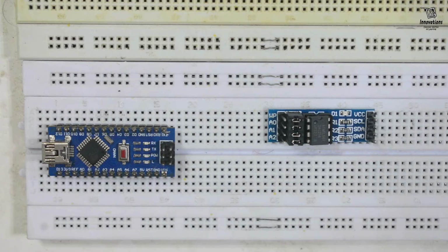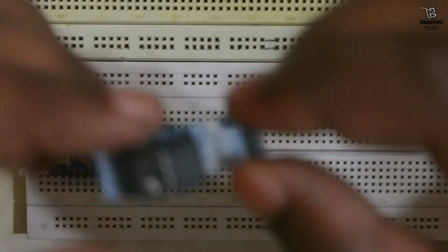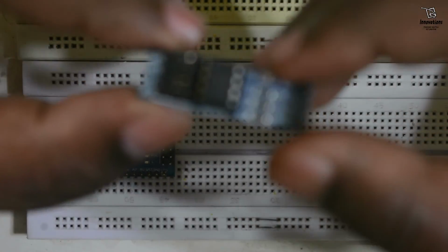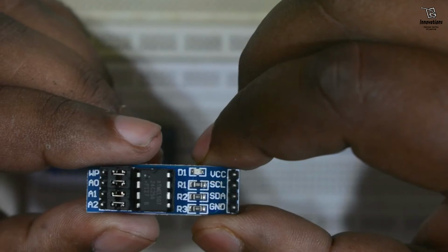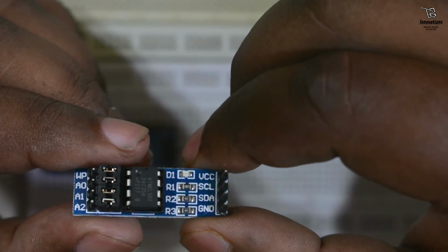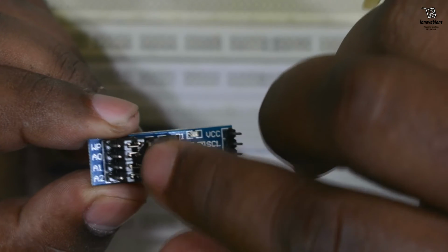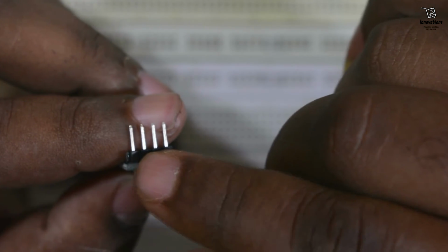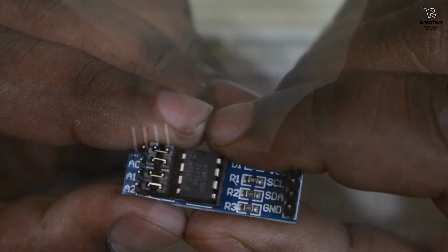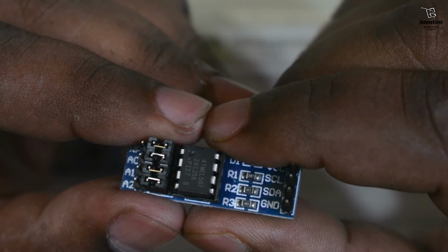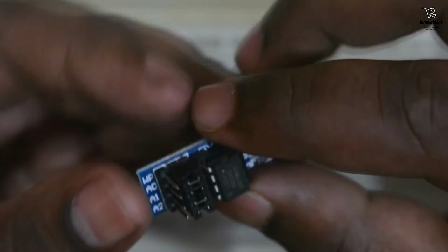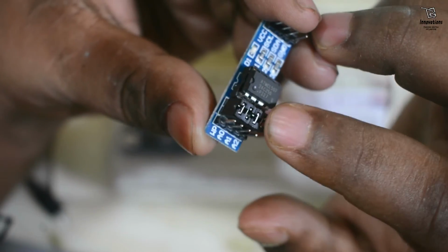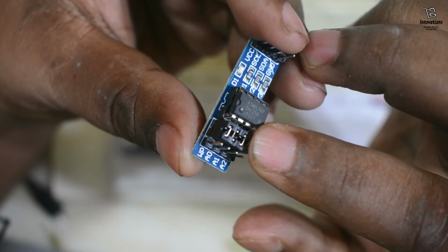So till now we have seen the module in the pictures only, but now I will show you the module in my hand. So this is the module. You have seen the same thing in the picture. You can see the jumpers here, and the pins to be connected with the Arduino. This is here. If I bring it closer, you can see the name of the IC, 24C256. Now what I was saying, these jumpers are used to set the address.